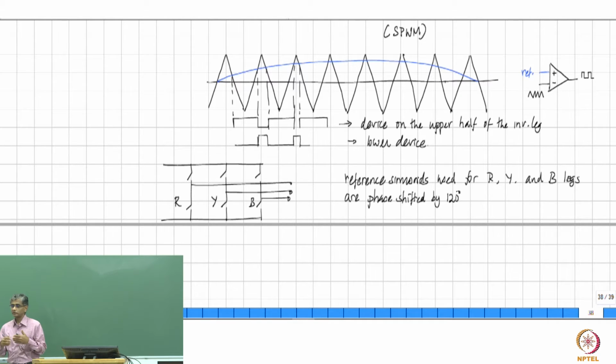Therefore, you are able to generate at the output of the inverter effectively 3 sinusoidal supply voltages that are phase shifted by 120 degrees. The motor induced EMFs are also phase shifted by 120 degrees, and therefore there is a meaningful interaction between the output of the inverter and the electric motor.